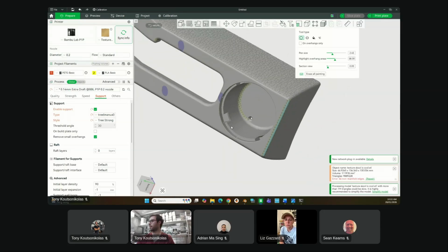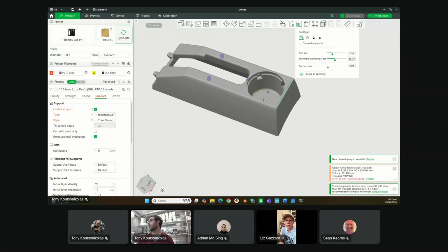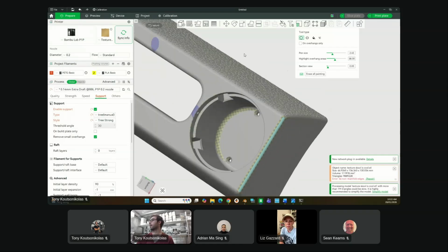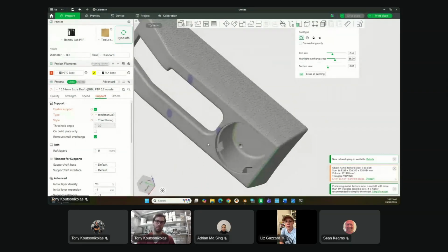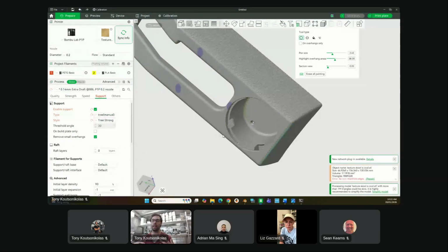Now, this is a cup holder, this bit, and this bit I think the handbrake goes into. Why does that need to be a fillet? It doesn't need to be. It could be a chamfer. It could be a tiny chamfer, maybe. It doesn't necessarily need to be a fillet, especially if we're going to print it in this orientation. And this is why, if you know how to do your own designs and you know how to do 3D printing, it's a game changer, because you'll be able to make these decisions while you're designing to make it easier to print.